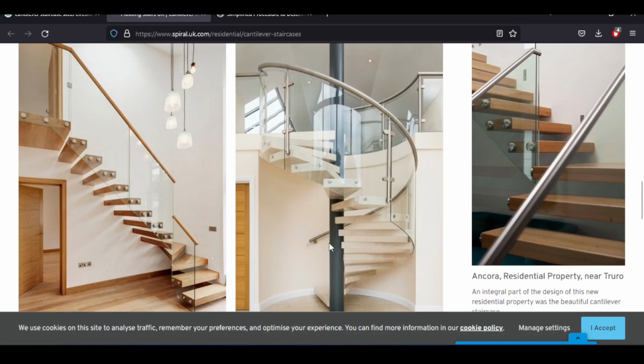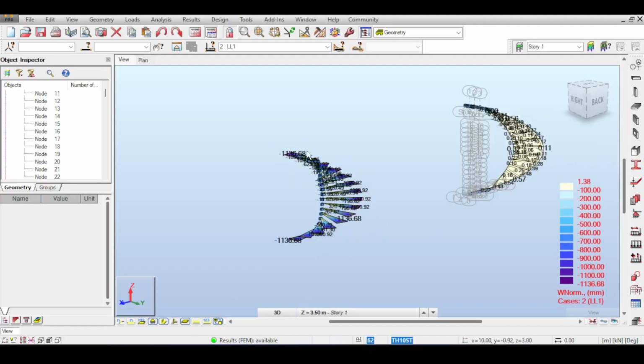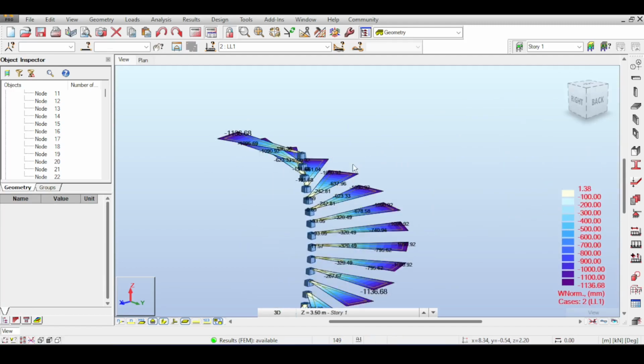You see, when you have cantilever staircases, the idea of having 1.25 meter large steps becomes an impossibility. Also, the steps are made out of wood or some lightweight material because steel itself is heavy. So I wanted to use this with care and use it in smaller spaces and when you have absolutely no other option. So I will leave this for you to think about. For me, I totally disagree and totally do not recommend this. I think I have said the same thing in the first video, but once again, this is yet another reason why not to use it.